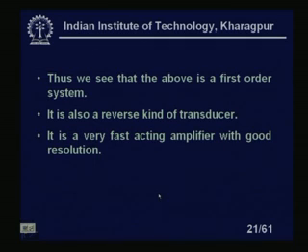If you consider the pneumatic amplifiers, it is a fast acting amplifier with good resolution. Sensitivity is also quite high, which we have already seen. And from the graph we can also predict that it has good resolution, used in precision measurements. So for very small displacements I can use this flapper nozzle system, because we have seen that for small displacement we get a large change in the normalized pressure output.